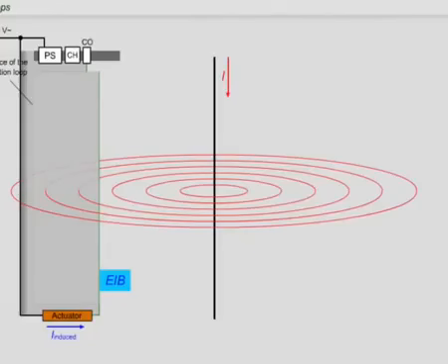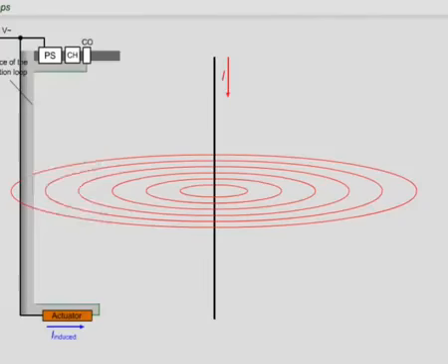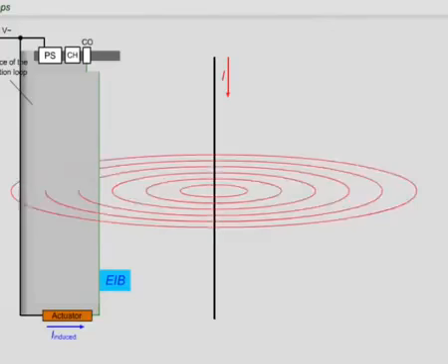The figure shows the 2 terminals of an actuator. As both cables, i.e. bus and mains cable, surround a relatively large surface, outer interferences can induce very high voltages in this big induction loop.